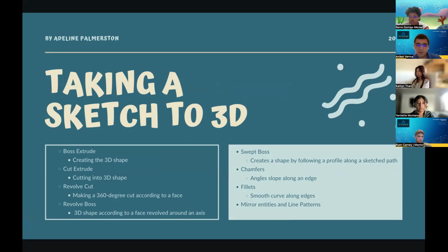Then you can have a revolve cut and a revolve boss, which is basically what it sounds like. You can take a drawing in 2D and you can revolve it to create something in 3D. As per a face or a sketch that you've laid out, and then revolve boss is creating something in 3D. That cut is just removing it in 3D.